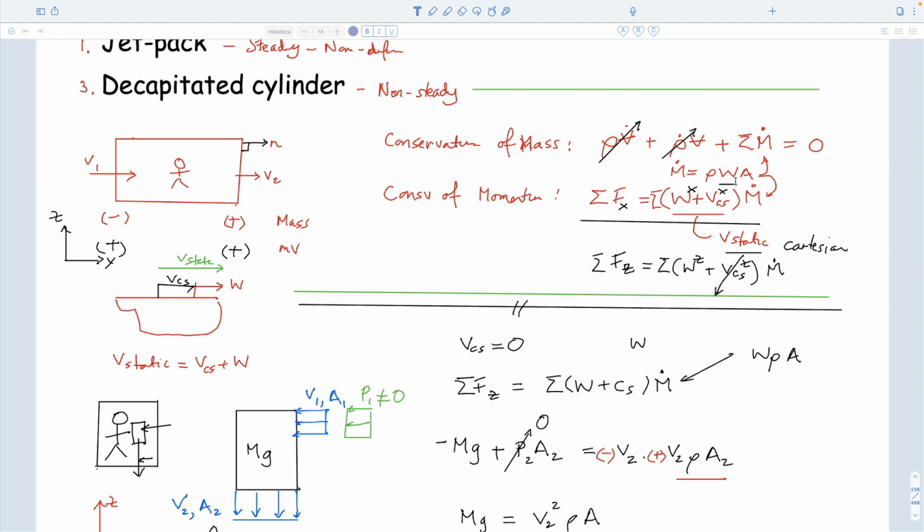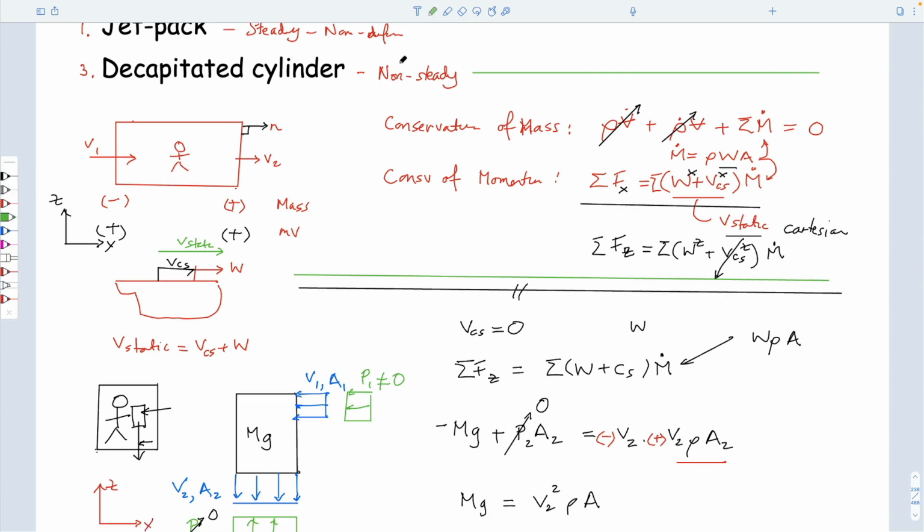We have mass flow rates in terms of the relative velocity times the area of the fluid coming out of it. And when we do that in terms of conservation of mass, we always do it relative to the outer normal. The outer normal allows us to gauge the relative direction. So the sign convention is for mass flow rates, a flow rate in is negative because it's opposite the direction of the normal to the boundary. I draw that on here. The normal to the boundary would be in this direction on this surface, right? So this is in the opposite direction. They're counter to each other. And so if you did the dot product, we haven't messed around with that very much and wouldn't have to, then this is negative in and positive if it's coming out.